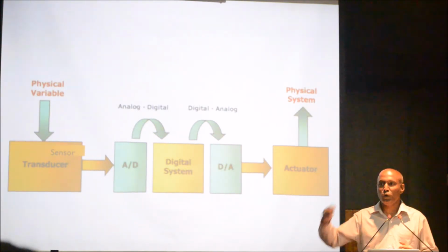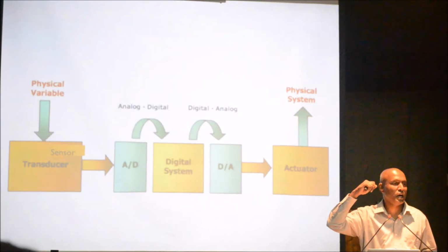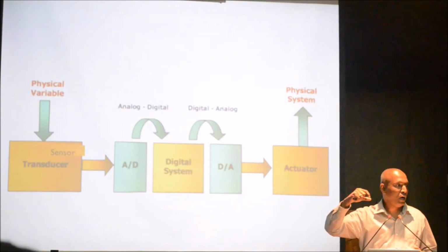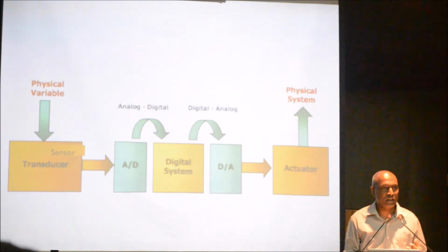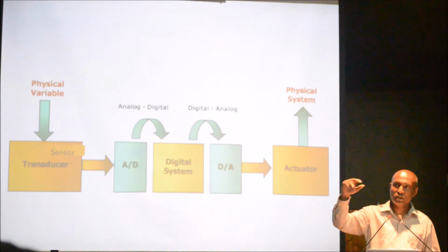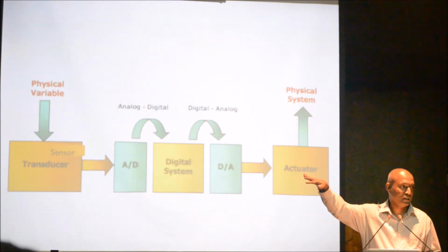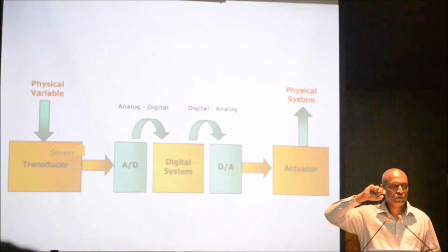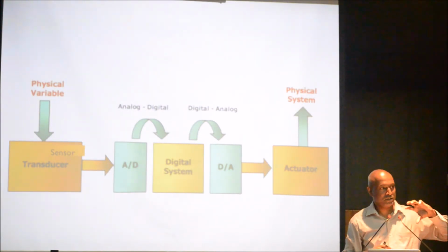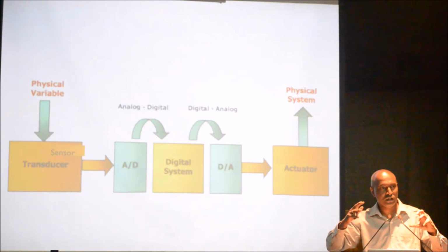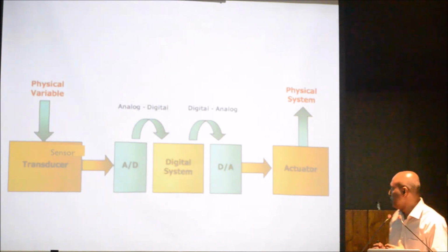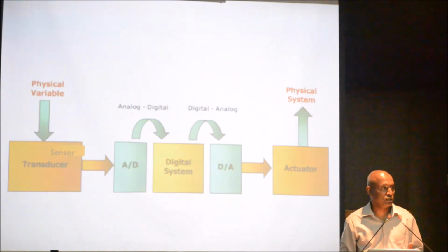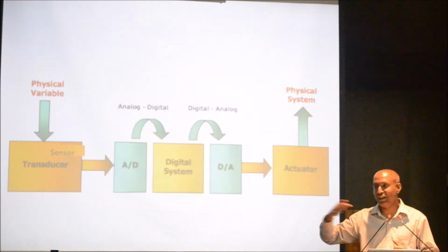An example is that if I want to close the door when the session starts, I will detect that the session started from a sensor, and then we'll process that data, and then we'll have a motor to drive that to close the door, right? So to drive a motor, we need to increase the voltage. So according to the digital signal we have, we need to drive a physical analog signal, which is voltage. Then the motor will drive and close the door.